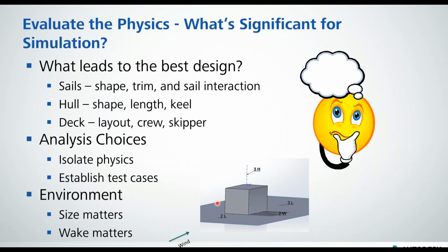It's ideal if you can keep it symmetric, if your flow is expected to be symmetric. And you need to go at least 3 times as high for your complete flow volume. Now, all these numbers are in our help documentation, so you don't need to memorize it. It's an easy matter to find. But this idea of 3 times the length in behind, that starts making a pretty hefty size of the box.